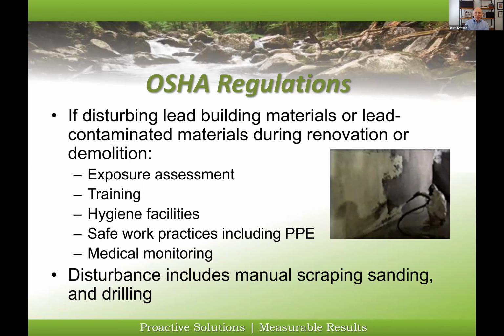OSHA also says if we are disturbing building materials that contain any concentration of lead, I've got to do this exposure assessment, the air monitoring. I've got to provide training. I've got to provide hygiene facilities for the workers, that would be to wash their hands and faces. They need to use certain safe work practices, including personal protective equipment.